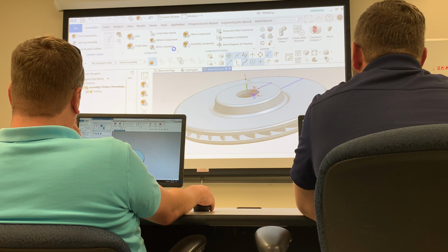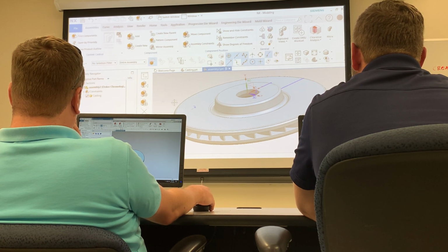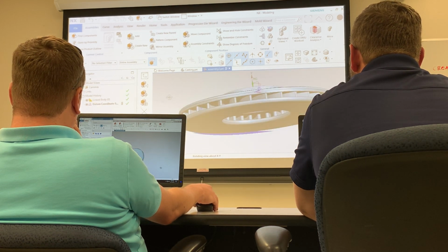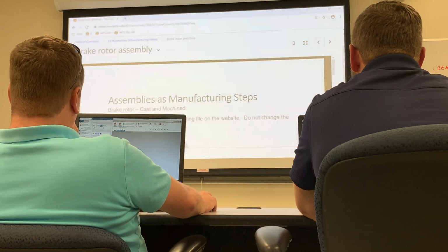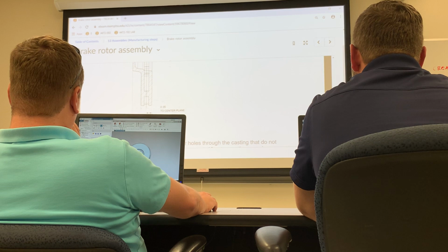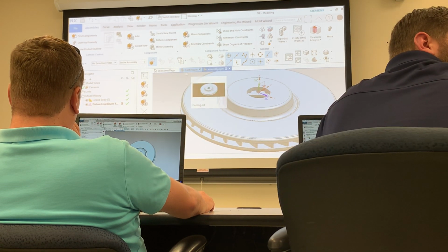Whoops. Man, everybody does that. Now, it should say in your constraints, you should have this fix on here. Where do you click for it? And then I'm just going to turn that off. So that'll keep this thing fixed in space. Won't let me select the constraint.